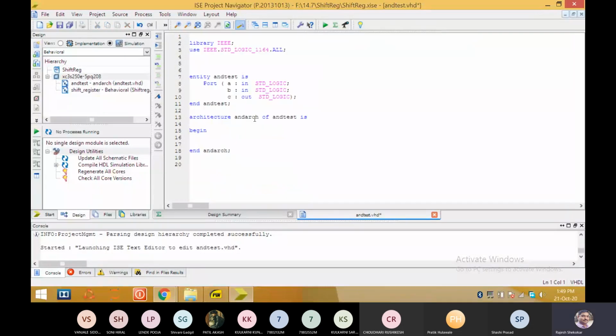Okay, it will look very simple and small then. Now in the entity you can see that a very simple name of entity we have chosen, and test. After that, the name declaration, we are writing the port information. It is generated by the wizard only. So this is the syntax for writing the port information: A, B, and information about the input or output nature